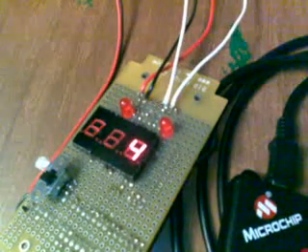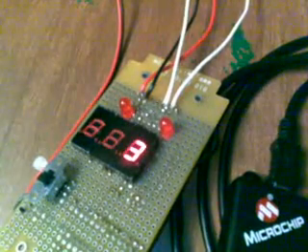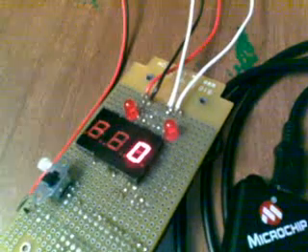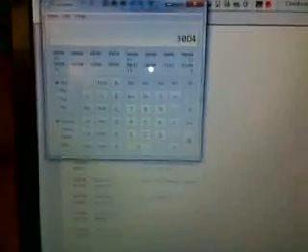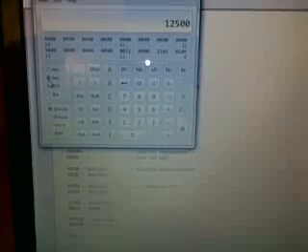0D4, that's not it, 30D4, which turns out to be, in hex, 30D4 is 12,500, which is kind of hard to see in the camera, but that's 12,500 pulses that it's seeing.